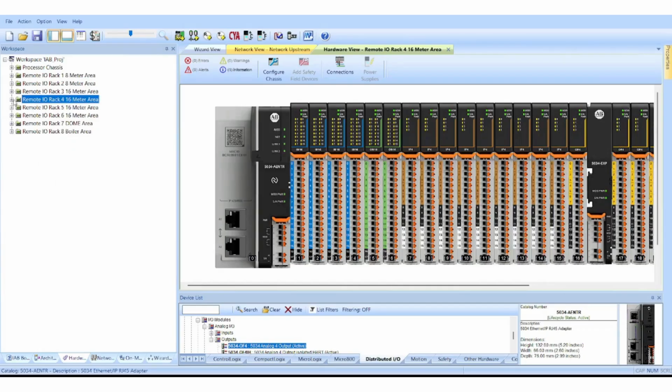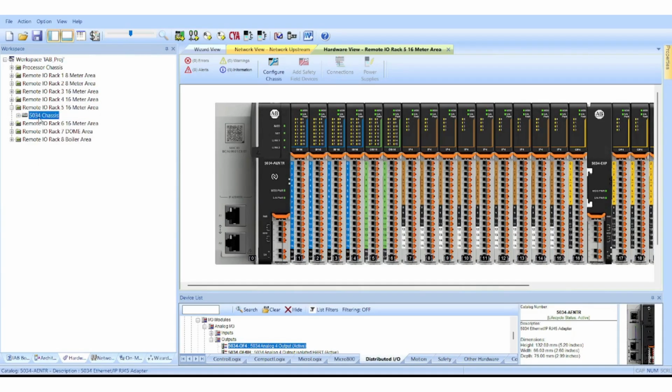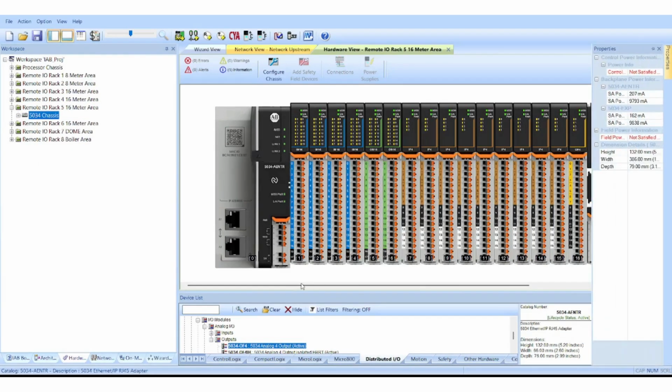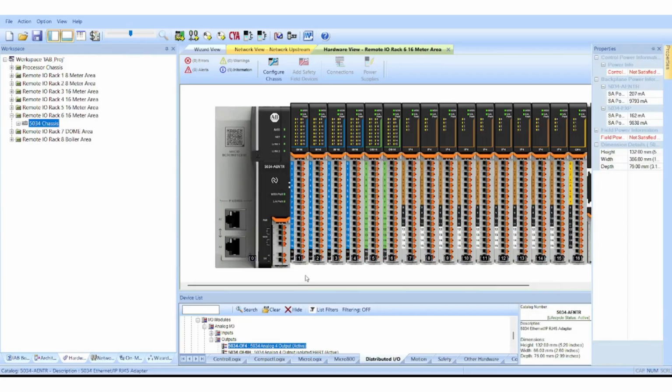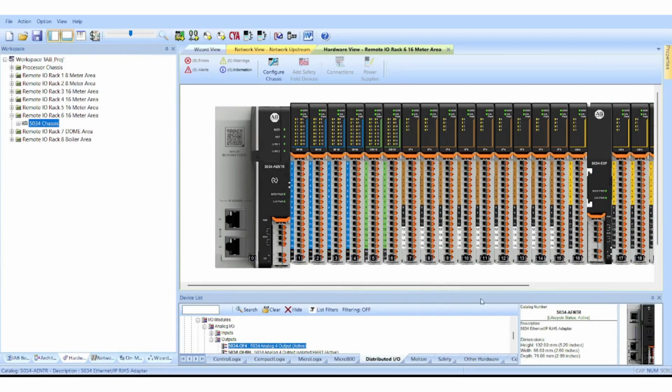At each stage, I recommend verifying the configuration rather than waiting until the very end. Check the controller, check the communication modules, check the remote I/O adapters and I/O modules, check the quantities, check the available spare capacity, and compare everything against the project I/O list, motor list, and architecture documents. Finding an error here is much easier than finding it during panel manufacturing or site commissioning.